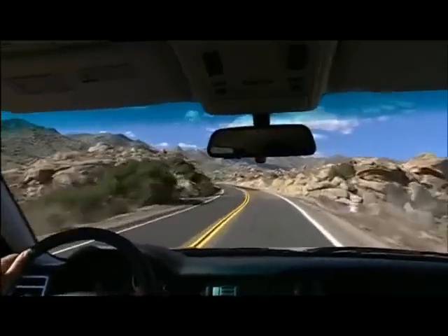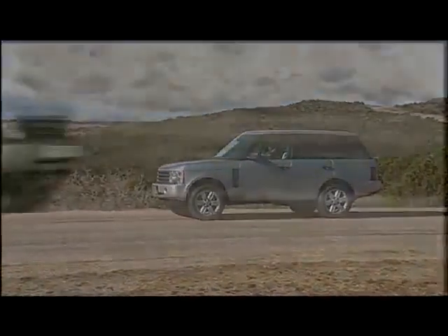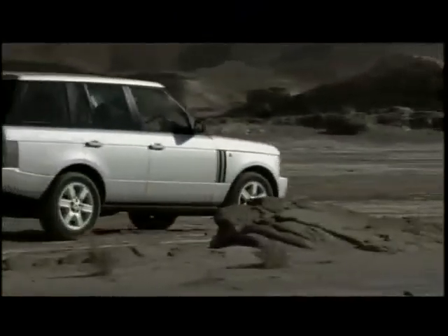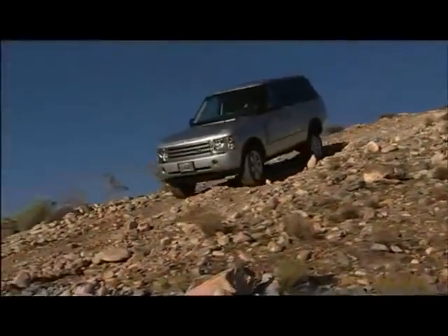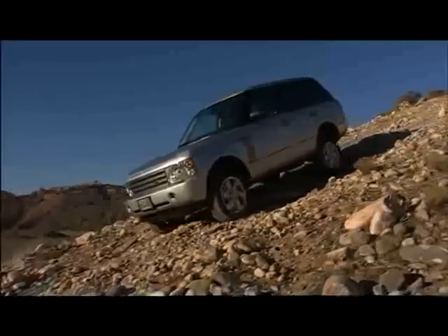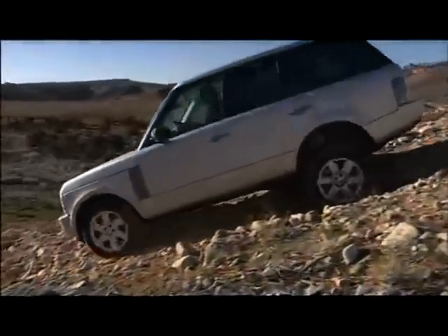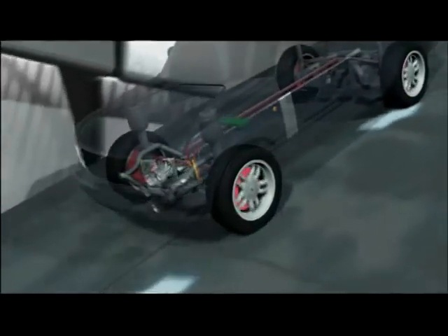Emergency brake assist activates during heavy braking, as in a panic stop. EBA applies maximum braking effort even if the driver begins to release pedal pressure. Hill descent control, patented by Land Rover, uses the all-terrain anti-lock braking system during descents. It prevents wheel lockup and applies the brakes when needed to maintain a consistent optimum speed. HDC is better than engine braking and driver input. It provides brake bias to the downhill axle and brakes each wheel when necessary.